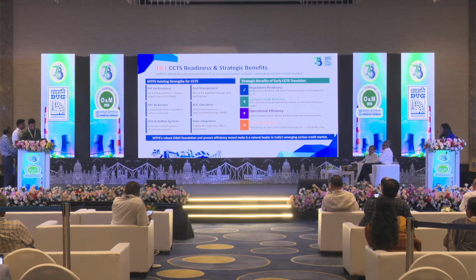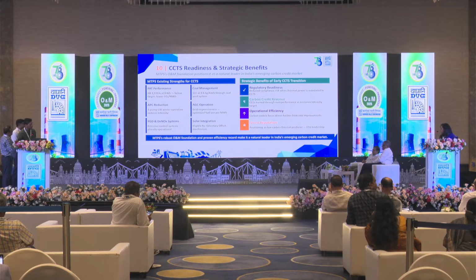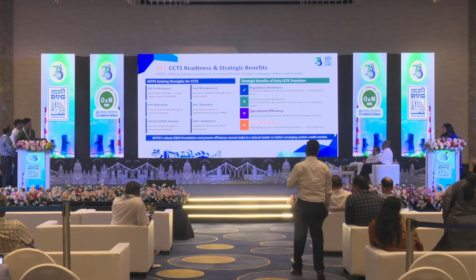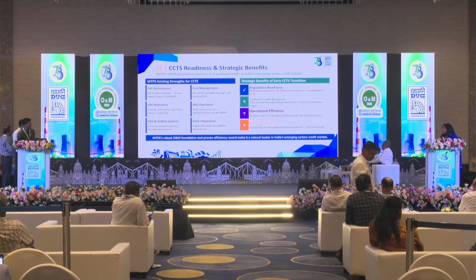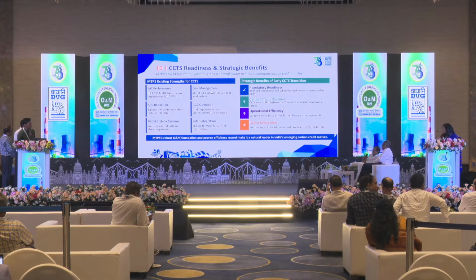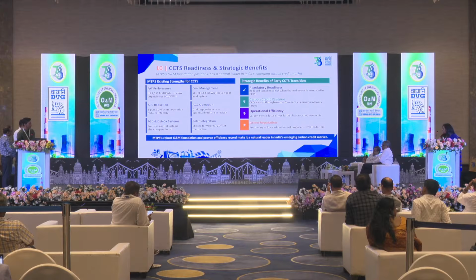Sir, the testing has already been done. The testing was done for 4 hours, and the 500 megawatt unit was run at 200 megawatt for 4 hours without oil support, with ABCD combination, with ABCD elevation. Can we do it every day? 24-hour operation has still not been tested. Only in the solar hour. Sir, it has been tested. It can be done.